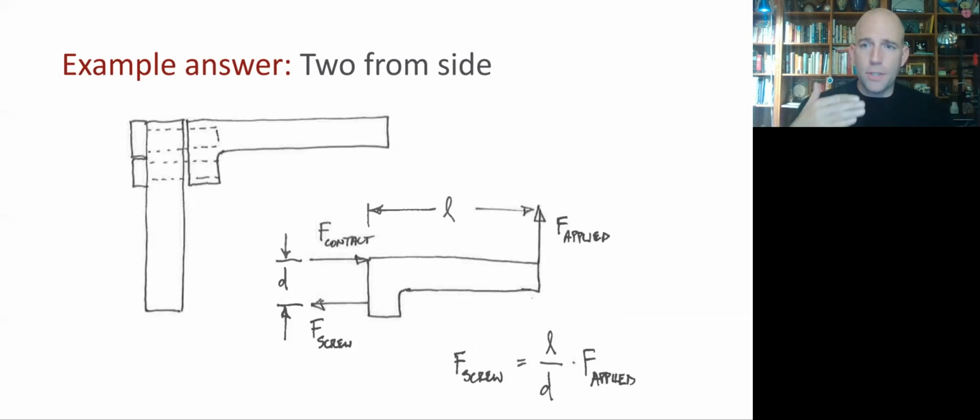So this is really similar to the third example from the last exercise, where we have some vertical plate and a horizontal plate, and then we have these 2 screws connecting the two. And that means that we can get this distance to be a little bit bigger than if we just had 1 screw coming from the side. And just like with the error amplification, the reason it matters here is because of the relative lever arms and how that affects the load multiplier.